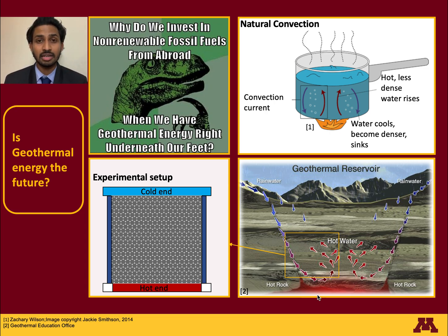The geothermal reservoir is modeled as the porous media filled in the enclosure with two active walls on the top and the bottom and with four adiabatic side walls. I am using a stack of spherical beads to represent the porous media. I have been performing experiments under different conditions to quantify the heat transfer rates.